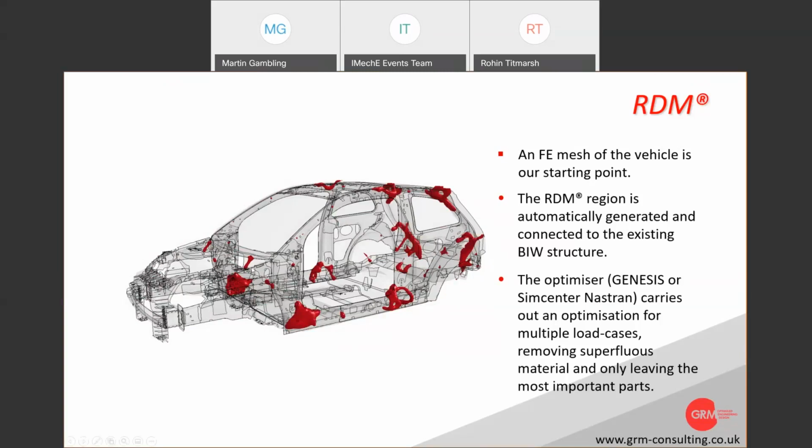And so what it's doing is it's removing almost all of that design space you just created, leaving just a small amount. So in this particular example, I think we're looking at around about 3% of all the elements that we just created remaining, and we get these blobs of material. So maybe you're now seeing why we started to call it magic custard. The yellow, very much fitted.